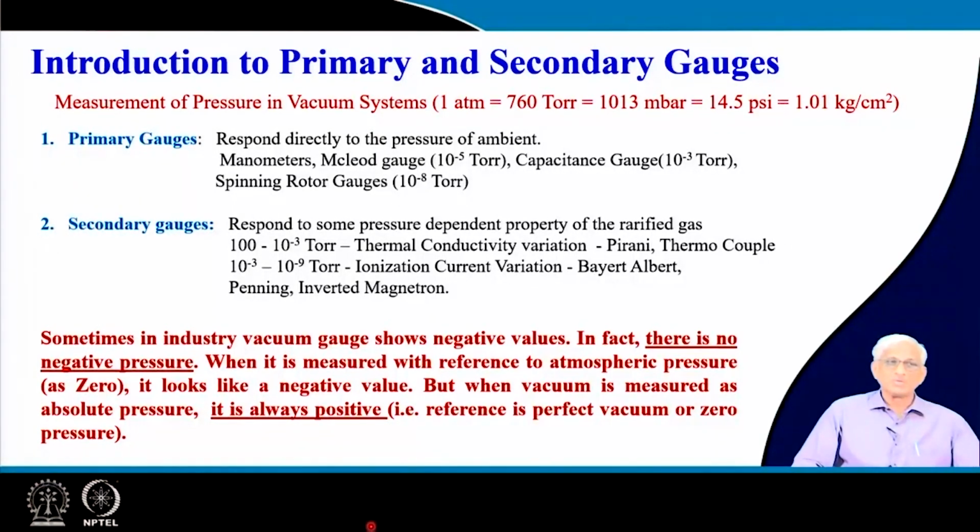Sometimes you will find very peculiar things in the refrigeration industry or somewhere. You will find lots of dial gauges where you need to evacuate refrigeration compressors, etc. When you are refilling, first you have to remove the gas with a vacuum pump and evacuate. This is a very standard procedure. This is one of the mega applications, on a large scale, of a rough rotary pump.